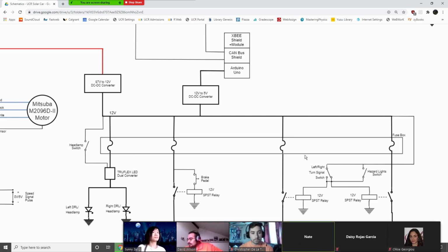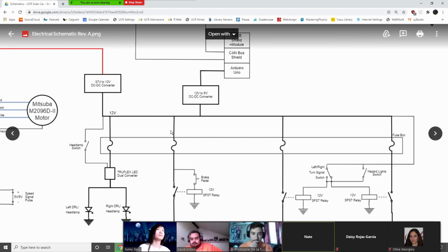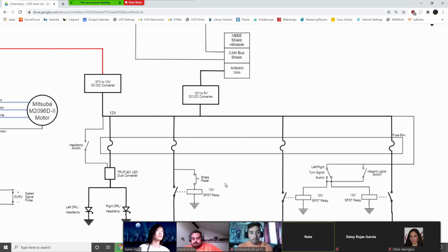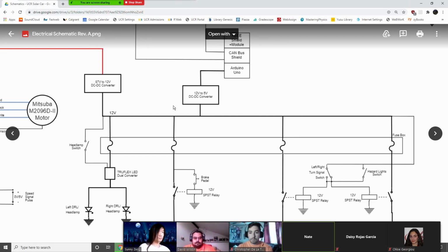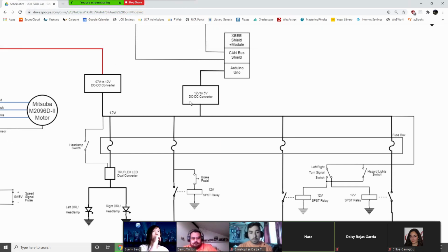Sure. Since we're just going over basic concepts at the moment, we're not getting into a lot of detail. If anybody here has done anything with serial communication, that's essentially what the CAN bus is. You get the same kind of communication with your USB ports. If anybody has done anything with an Arduino Uno or microcontrollers communicating through UART or SPI or I2C, it's the same thing. The only real difference is that there's no master-slave relationship. Every node basically arbitrates which one goes first.